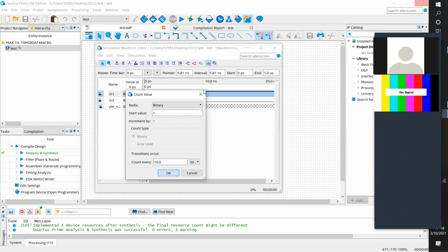After you set up all the input waveforms, like now we have 2 inputs, that means we want to check in the truth table 0,0, 0,1, 1,0, and 1,1. That will be 4 kinds of inputs. And if we have a truth table that has 3 inputs, then we actually need 8 kinds of inputs. So we have 2 to the power of n.